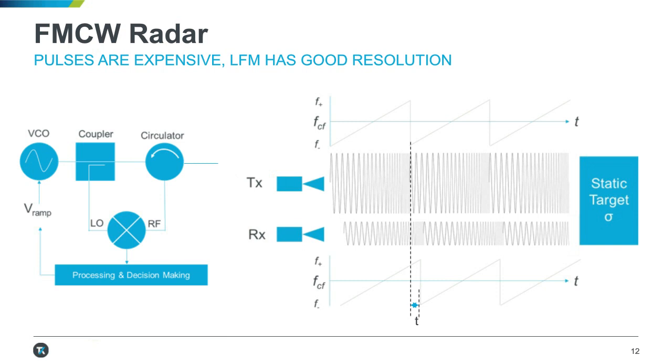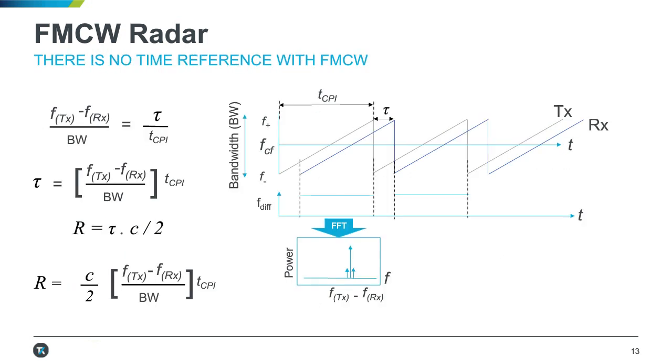When we transmitted the pulse, we had a defined start time, i.e. the start of the pulse transmission, and then we could simply compare that to the receive time. With FMCW, it's not as easy to compare those times because we're dealing with frequency ramps.